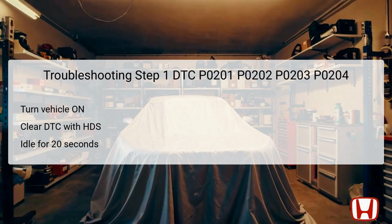This is essential to allow the engine systems to normalize and to see if the DTCs reappear. Once you've done this, check for any pending or confirmed DTCs again using the HDS to determine the presence of the fault condition. In this step, the focus shifts to testing the injector's internal resistance.